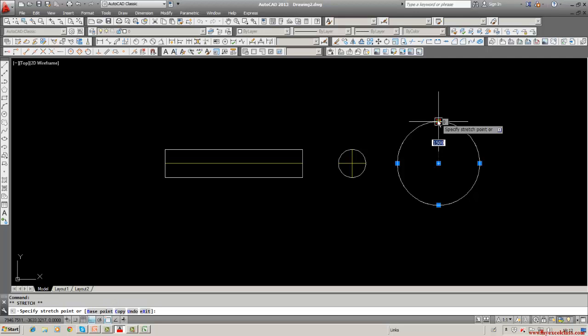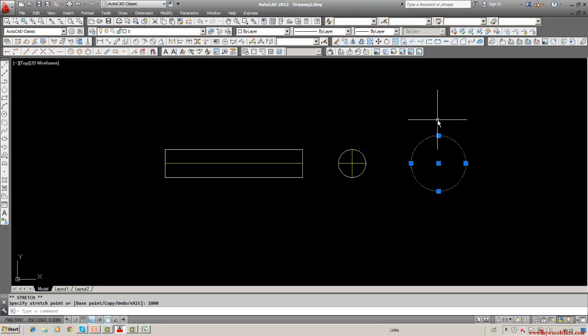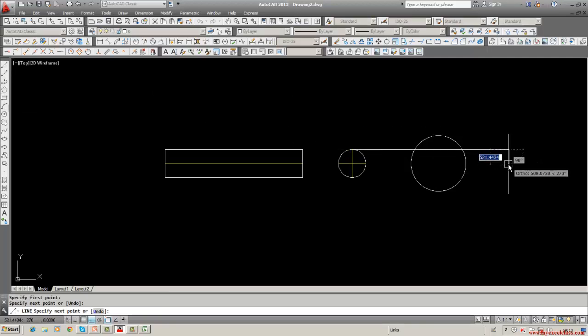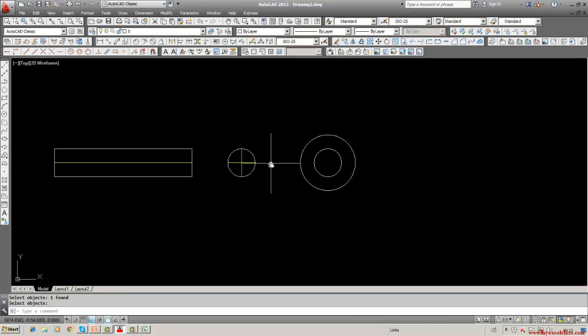Will further reduce. This is the bearing diameter, and the bearing will have a hole. It's a simple bush bearing, let us say. And the hole's design size will be the same as this diameter, and we can draw that. Draw a line, a circle, perpendicular to that. This is the hole. So the side view of this.